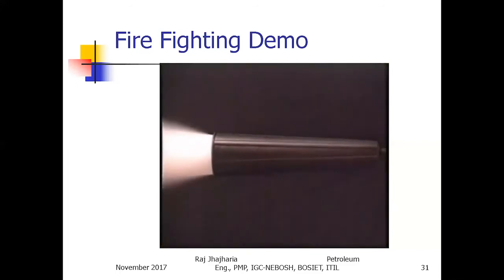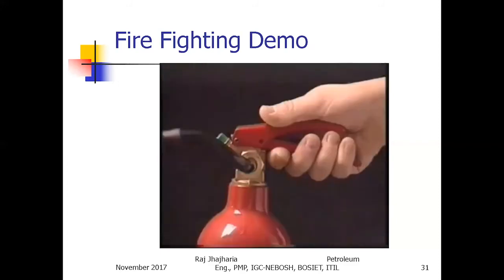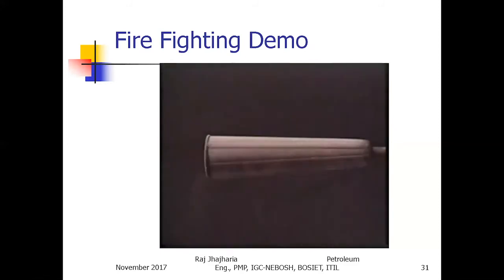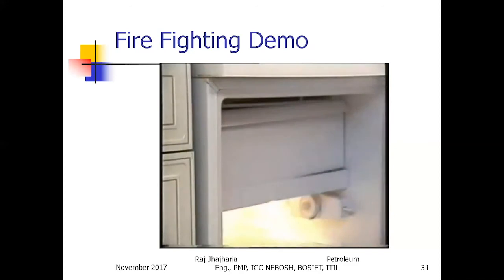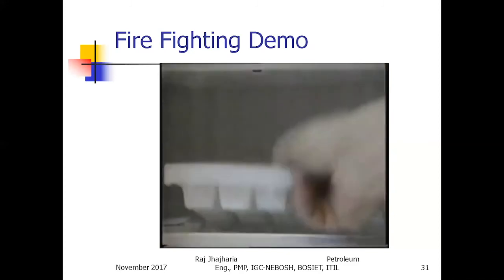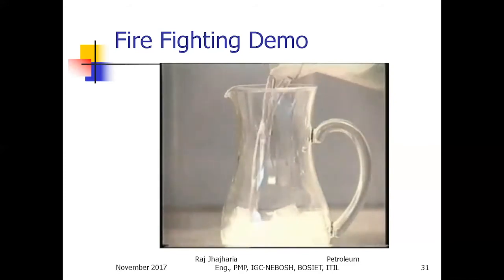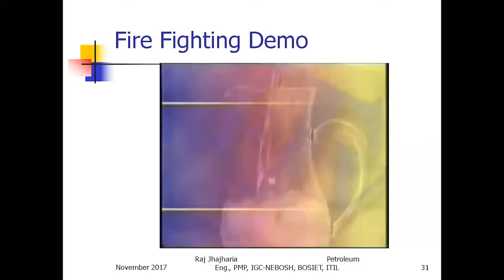This gas is stored under extremely high pressure, which makes this extinguisher very noisy when it's being fired, which often comes as a shock to the operator. While it's being fired, the discharge horn of the extinguisher gets very cold. In fact, it can get sufficiently cold for your hand to stick, which may cause frost burns. It's a little like when you take ice cubes from the freezer, they stick to your fingers, except the temperatures are much lower, so the damage to the skin tissue is worse.